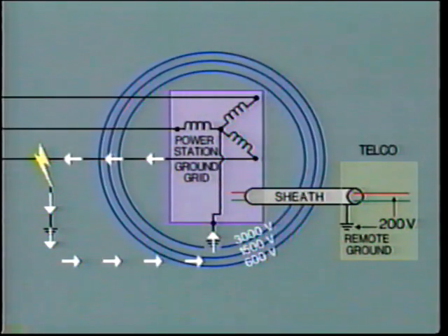In the last segment, we looked at the conventional type of protection, which is provided by the telephone company on all telephone circuits. We noted that, in general, these devices alone do not provide satisfactory protection for voltage rises above 1,000 volts. But we have already seen that in many substations, voltage rises above this level can appear on the telephone system during fault conditions. For this type of installation, additional protection schemes have been developed.